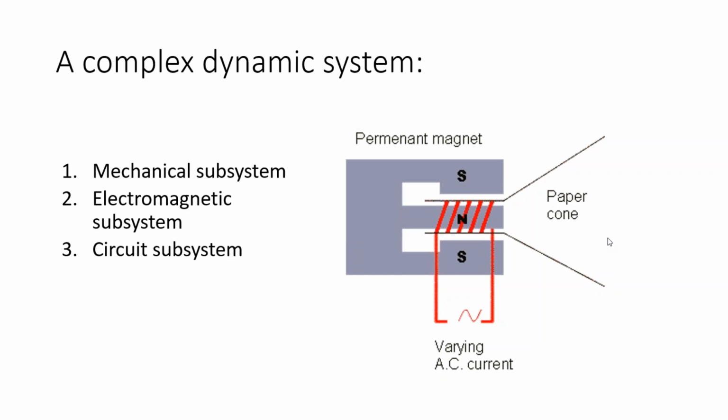So our whole goal is to use EMS to compute magnetic forces for a variety of coil displacements and current magnitudes, so that later on we can take these results and plug them into a mechanical simulation to predict the overall dynamic behavior of the whole system. This is the way you would use EMS if you wanted to simulate the whole system, and how EMS would help you bridge different subdomains.